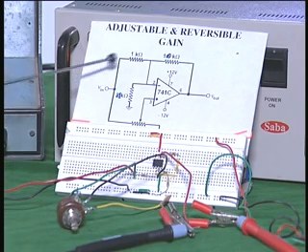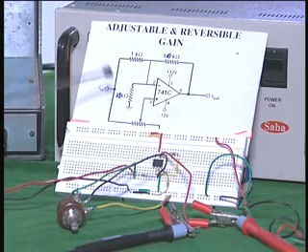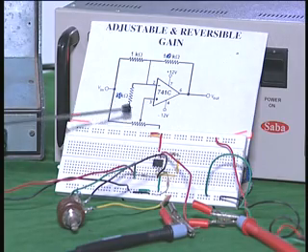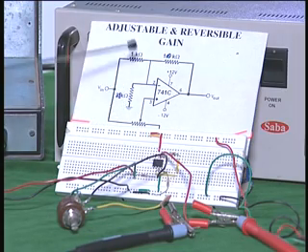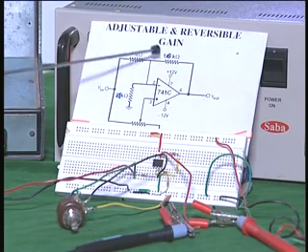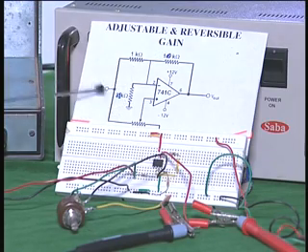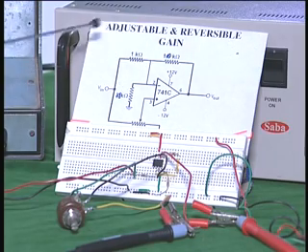So it is a very simple configuration with only 4 resistors, 3 of them fixed resistors and 1 a variable resistor, and by changing the value of the potentiometer I am able to vary the gain of the amplifier from plus 10 to minus 10. I have used here n to be 10. If we want to change the gain to some other number, you can very easily do so.